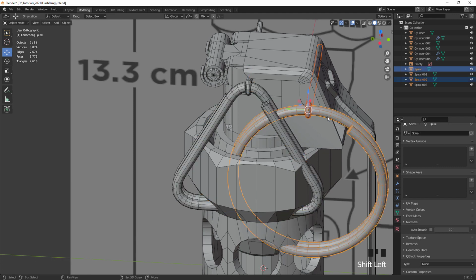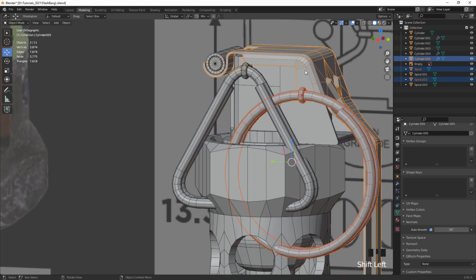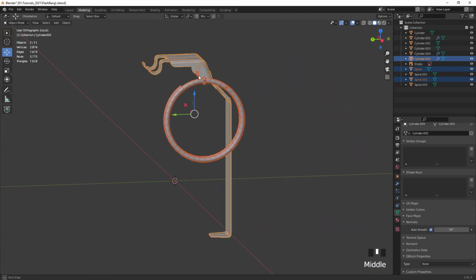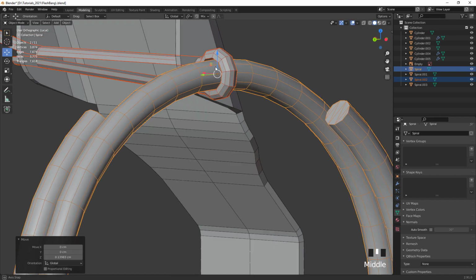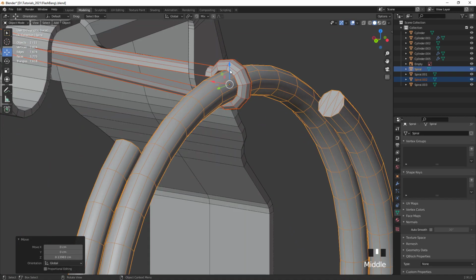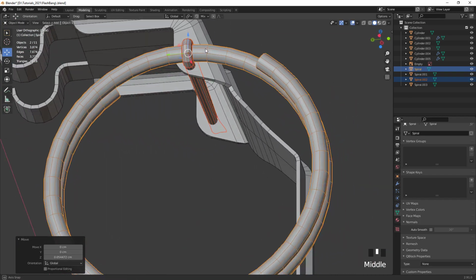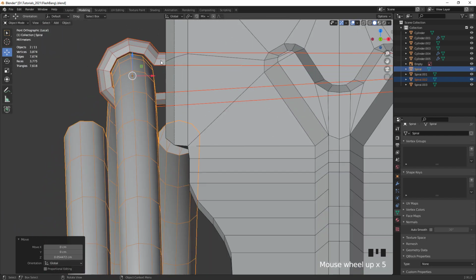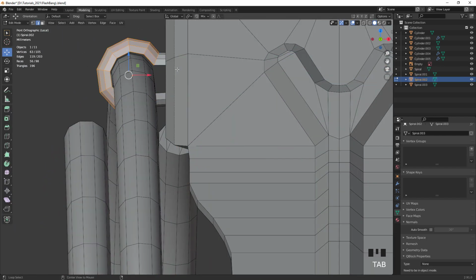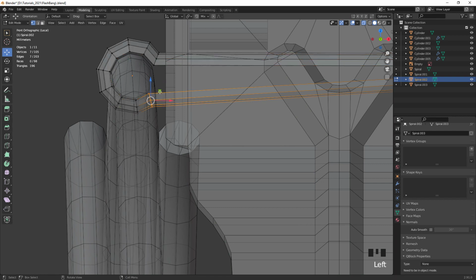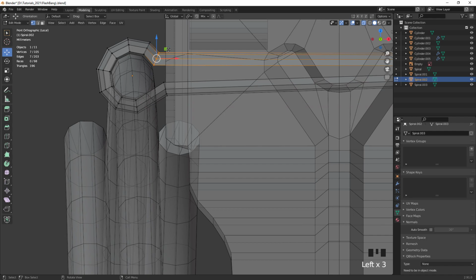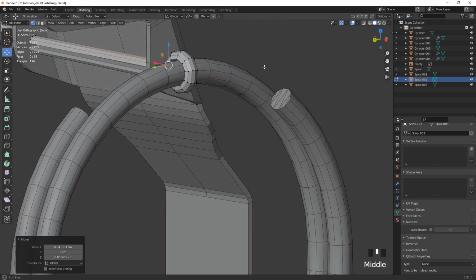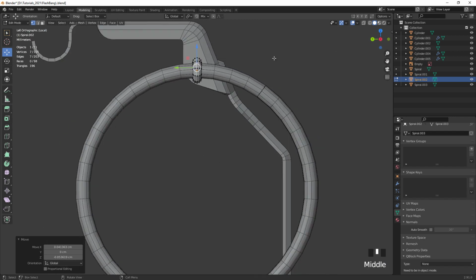So let me just select these two objects here, actually together with the lever, and isolate it so that we see more where we have to position it in order to put a hole in there with a Boolean operation. So I'm gonna just now select this here again, and while we are in the X-ray mode, I'm gonna select these vertex points and bring that closer together. Otherwise we have to drill too much of a hole in there.